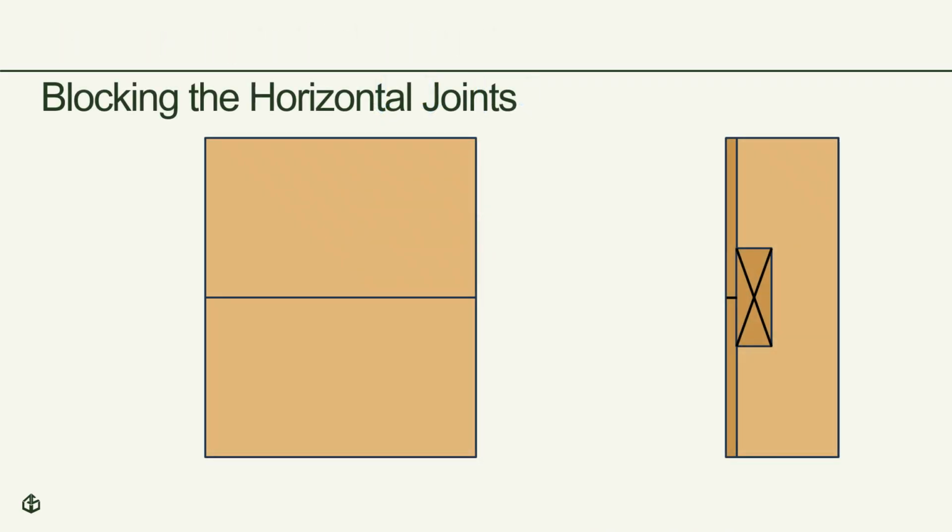In the last illustration, we presumed that the brace wall panels were constructed properly to prevent racking. A critical part of that is having horizontal joints within the panels properly blocked. Otherwise, as shown here, racking may still occur. Blocking also requires sufficient nailing to transfer the load to the blocking and make the sections on each side of the joint act as one.